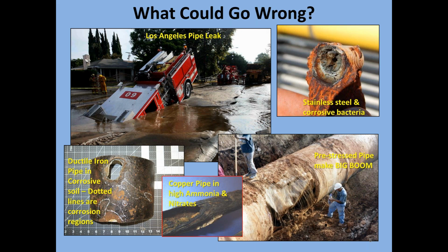So if you take a magnet and run it over the surface of that pipe, you will feel the magnetism disappear when you get to the areas where the iron has been leached out. Basically, the iron leaches out to the point where the internal pressure inside the pipe breaks through that mortar lining and pops the cork of the graphite.